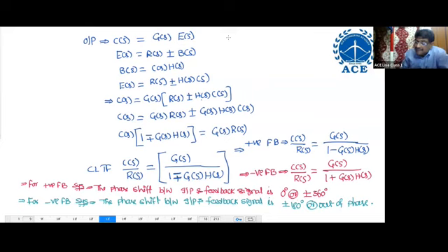They'll design the feedback network such that there should be 0 degrees and 180 degrees only. You don't get anything in the middle. You studied this in amplifiers, na. In oscillators, what do they do? They'll arrange the component values, RLC values, such that the phase shift should be either 0 degrees or 360 degrees or 180 degrees only. Okay, na? Next, comparison